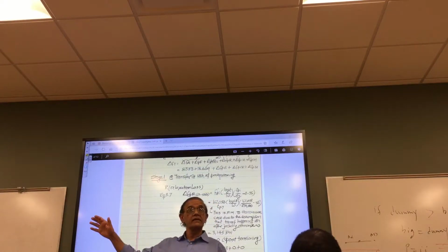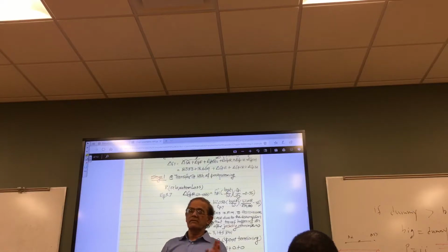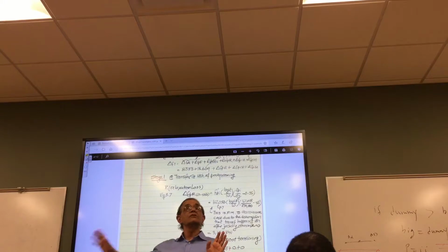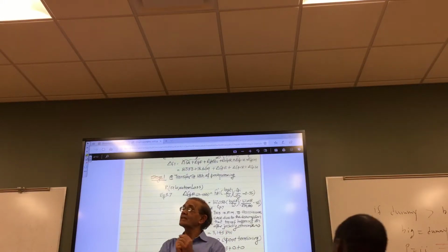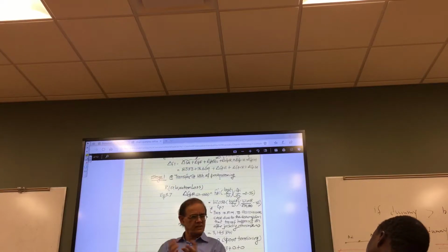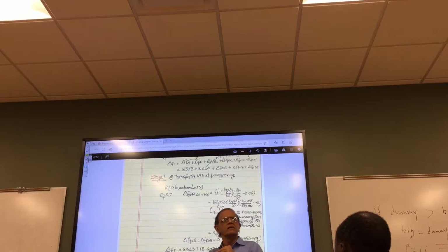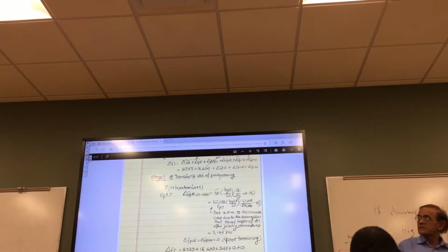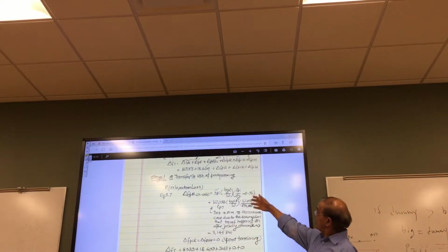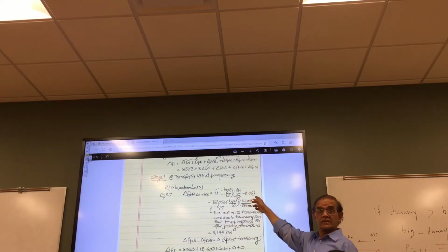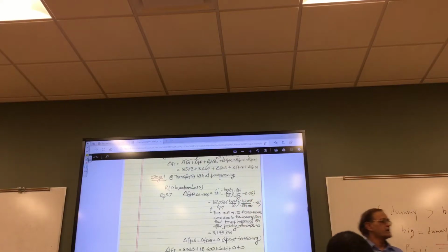If you know the 28-day strength, you can calculate the strength depending on the time. But if you flip that expression, you can find the time if you know the strength. That would have been perfect if somebody had thought about that. But again, we didn't discuss it in class, so no need to worry if you did not do it. Normally, you are given a time. If you're not given one, you can calculate the time. So anyway, 18 hours is given.